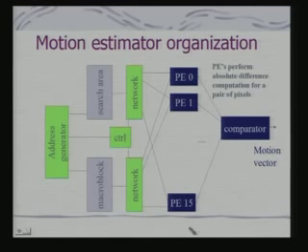The interesting thing is that this is a network which connects the data from the macro block and the search area to the PEs depending on how the scanning is taking place, because you are scanning the macro block over the entire search area. Depending on the scan, this interconnection has to be done, and which data is to be selected is given by the address generator. So, the address generator is actually taking care of the scanning task.